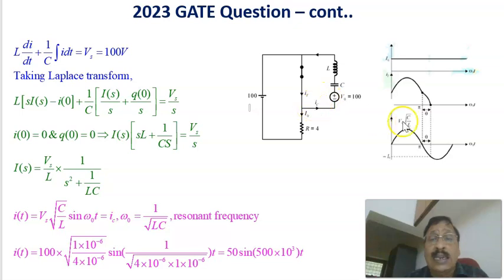Once this current, that is the opposite current, reaches the load current, flowing in the same direction as the load current, then the device current will become zero. At this instant, this reverse current is equal to the load current, so the device current, this current plus the load current, is equal to zero. The device current equals zero at this moment.